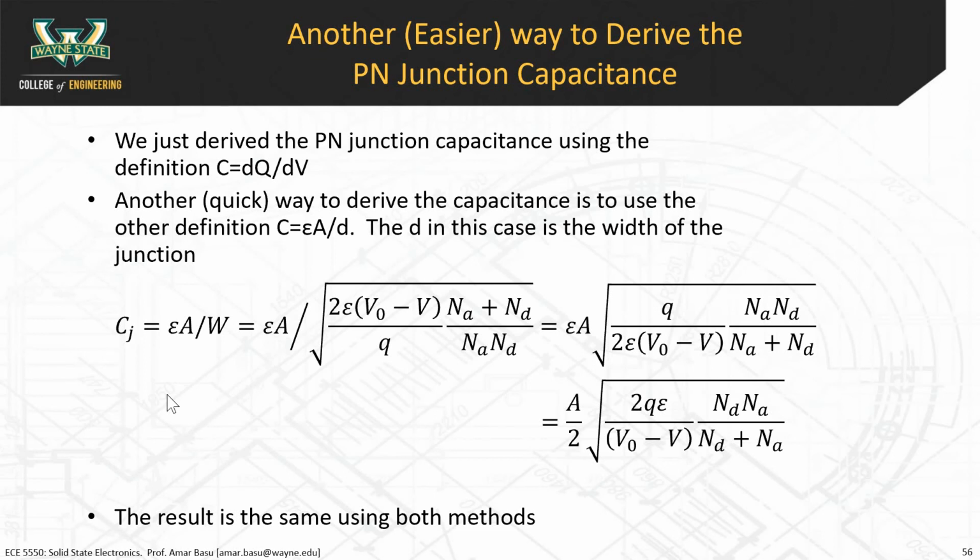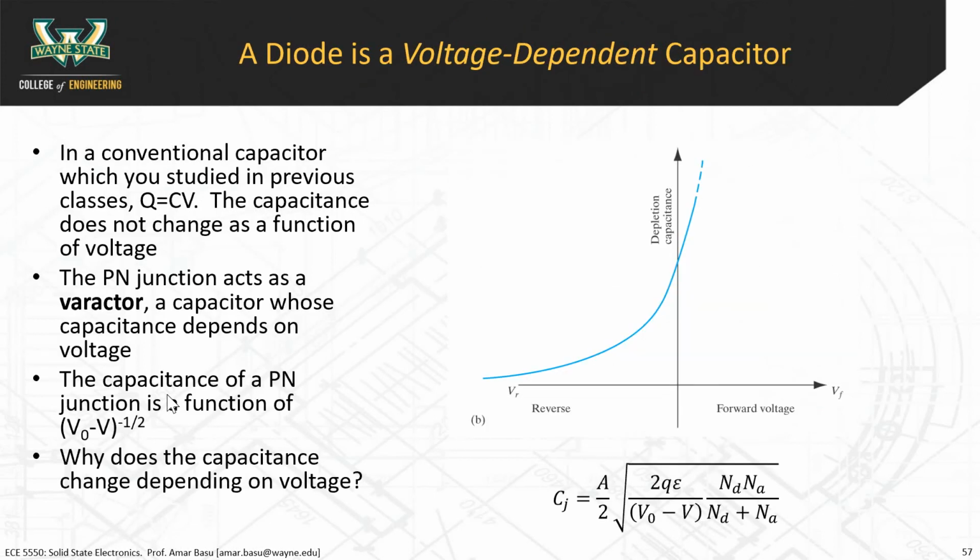All right. So at this point, you can think about that when you have a diode like this as part of your circuit, whether that diode is forward bias or reverse bias, it doesn't matter. I've drawn this in the reverse bias state, when we draw the equivalent circuit for it, we have to consider that it has a capacitance associated with it.